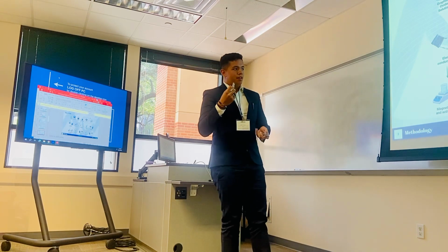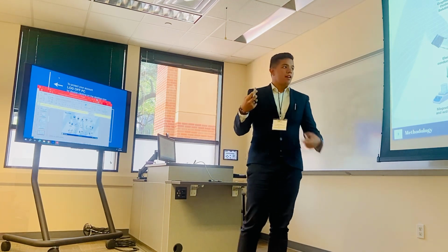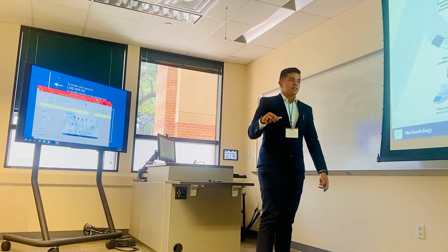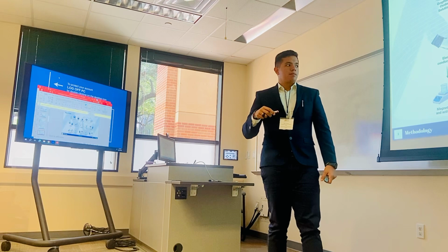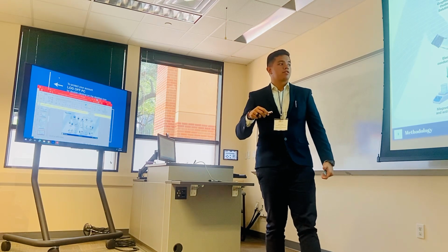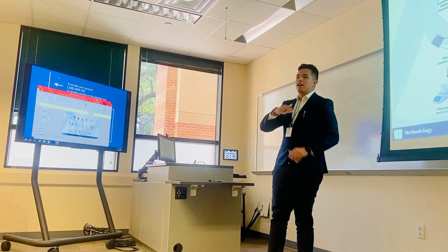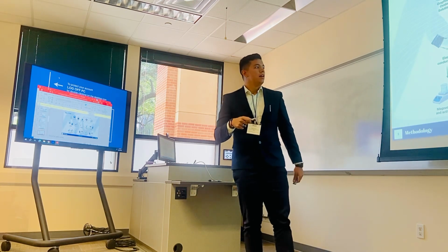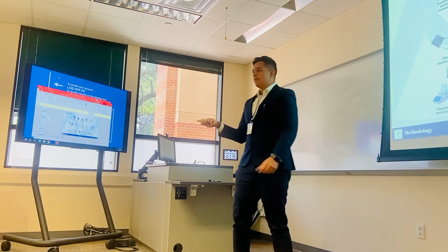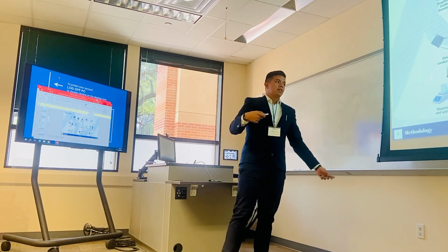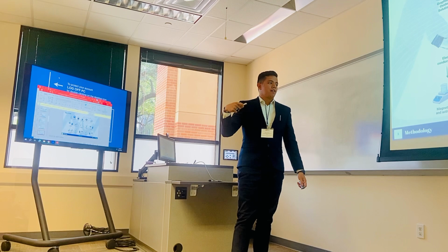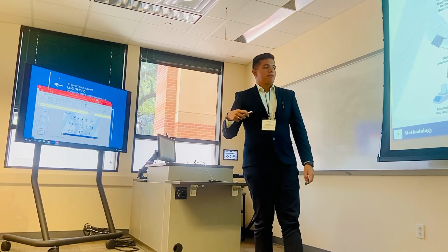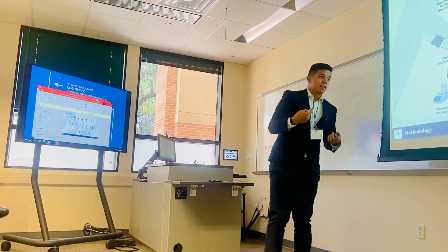So we wanted reduced graphene oxide, and for this we used a solution with sodium borohydride. Kind of the same thing happens here: when sodium borohydride is diluted in water, some of the ions actually rip off functional chemical groups of the graphene oxide coated textile, thus giving us more conductivity, as we'll later see. And then we functionalize the device by also dipping in solutions of PBA and activated charcoal, respectively, to give them the sensing properties that we wanted.